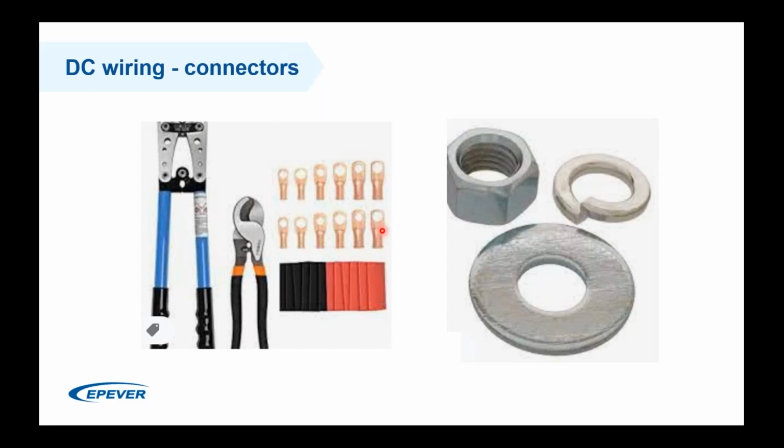Then you have to use a special crimping tool to attach the lock to your cable. Sometimes I've seen people use non-standard tools like a hammer. Okay, it works at the beginning, but the problem with that kind of pressing is that the amount of wire that touches the lock is actually lower than the thickness itself. So you have a very high resistance at your joint, and it will get warm.